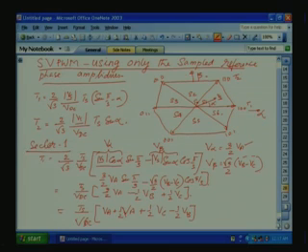So, this Vs, the sampled reference phase amplitude, is generated with values along the A, B and C axis. So, if you see here, finally it will be equal to Ts by Vdc into Va minus Vb. Okay. This we can further simplify. Let us see, we can write it like this.